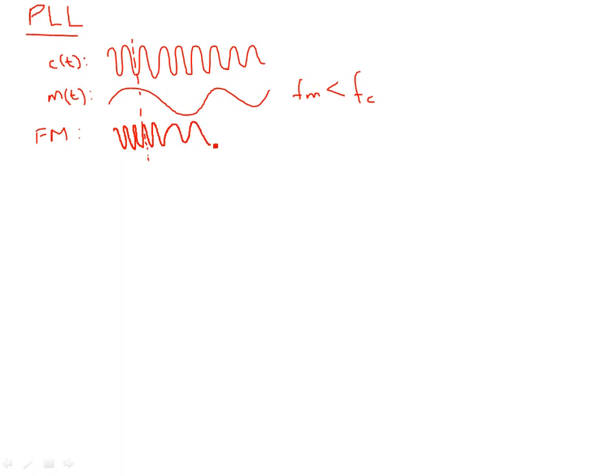Okay, where the message signal has a low amplitude, and then when there is a high amplitude again, you have more bunching of frequencies, more bunching of waves together. So it's like a high frequency over here. So the instantaneous frequency is being varied with respect to the message signal, without affecting the amplitude. So you can see where the amplitude is high, you have higher frequency.